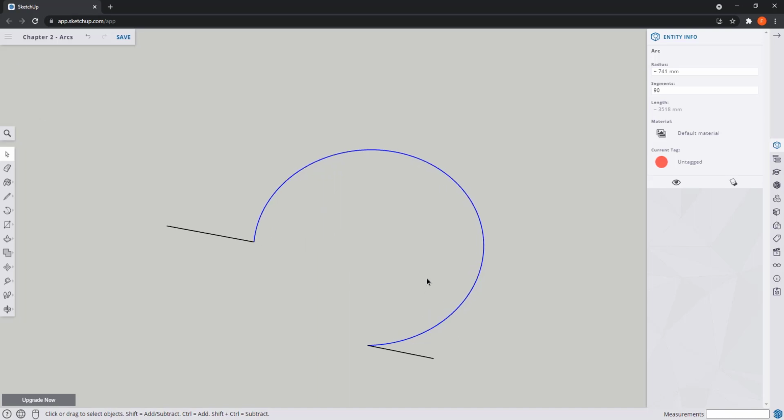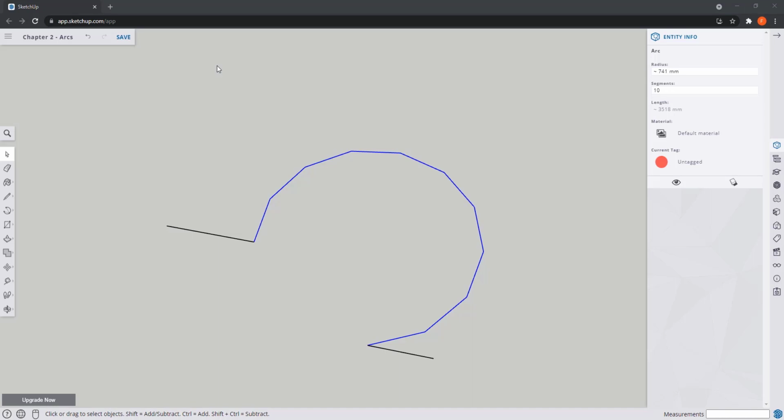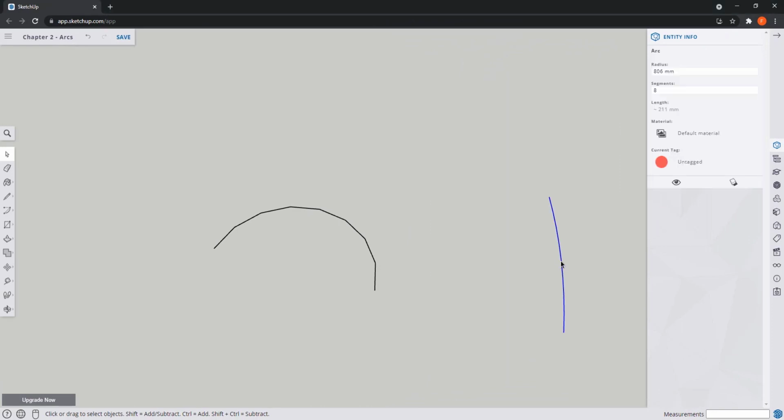Now you may ask yourself, for what reason SketchUp divides arcs and circles in segments? Good question, and this is regarding the usage of RAM memory. If you have a lot of circles in a project with a big number of segments, the workflow may slow a bit. So, the point here is to specify the minimum number that still looks like an arc. Another important tip: the higher the angle, the higher the number of segments we should use.